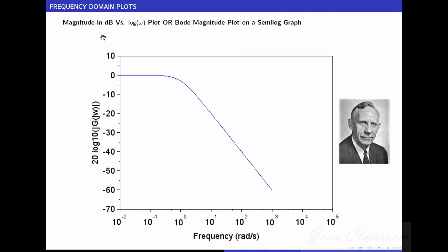So this understanding is necessary. Anyhow, plotting this magnitude converted to decibels against the frequency in logarithmic scale, we call it the Bode magnitude plot. So therefore, so far we discussed only about the magnitude.